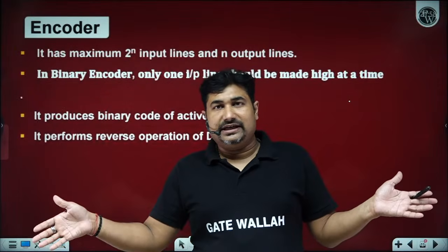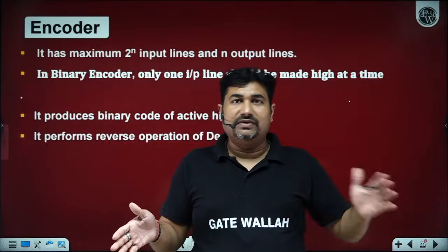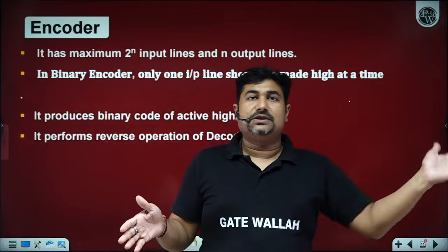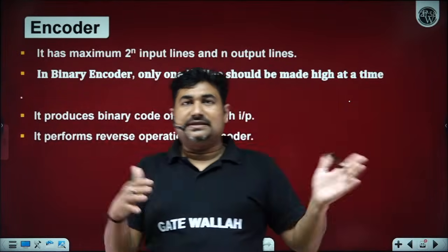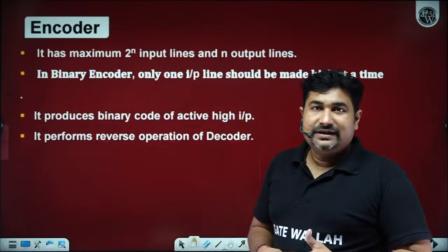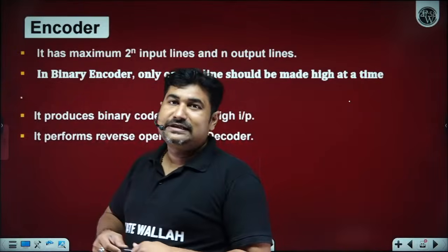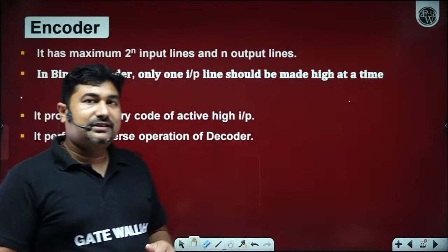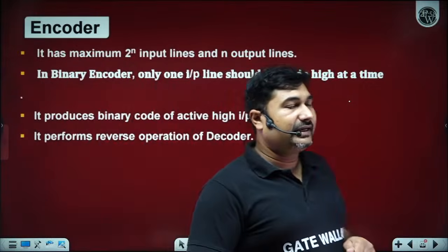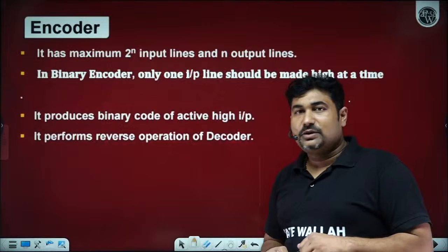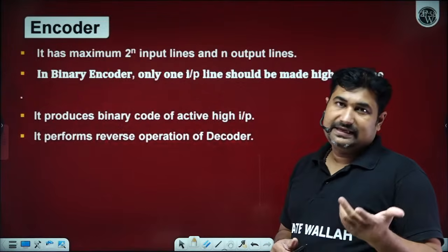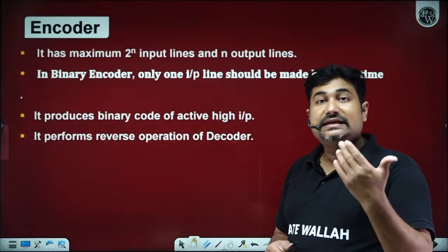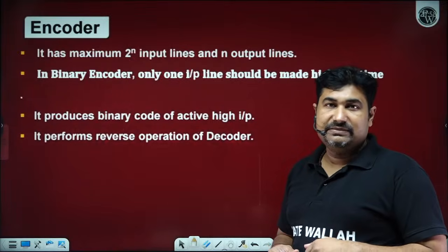If we get the input 0001, we will get output 0100, binary of 4, so plus 3, excess-3 code. So can you design a binary to excess-3 code converter circuit? Yes, sir. Now you can design any desired combinational circuit with the same steps.